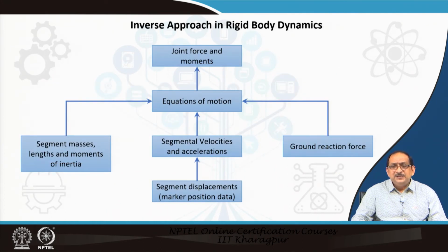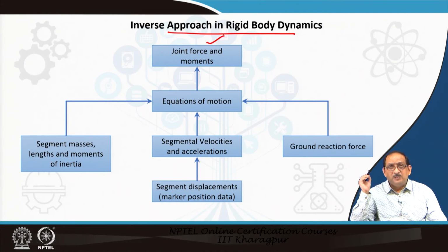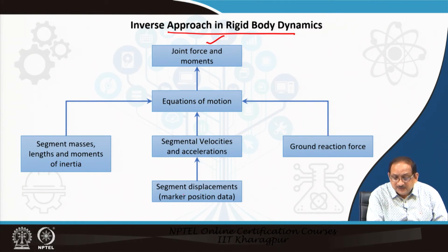Let me summarize the inverse approach used in rigid body dynamics to find out joint forces and moments. We can start from the segmental displacements that are obtained from the marker position data from the gait analysis.